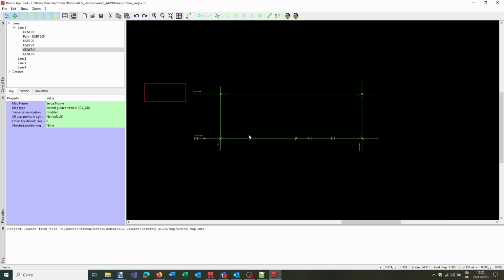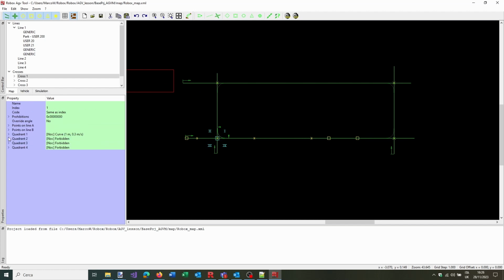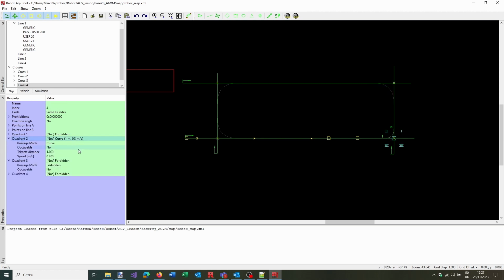Okay. Now, because of this big AGV, I'm quite sure that these kinds of curves are getting a little too short, and the AGVs will not be so happy to curve so much. Actually, this is just a fake AGV, so it's not a real problem. But in case of a real AGV, we must take into account that it may have a maximum curve angle, and so we must prevent this.